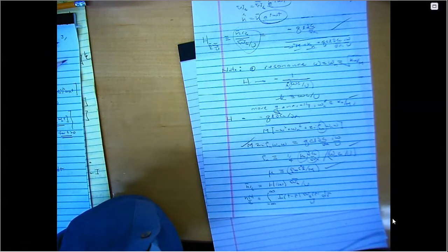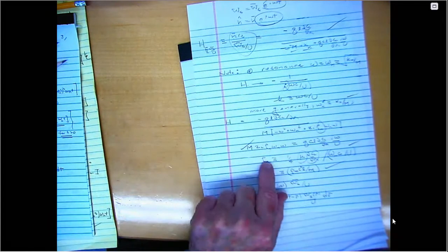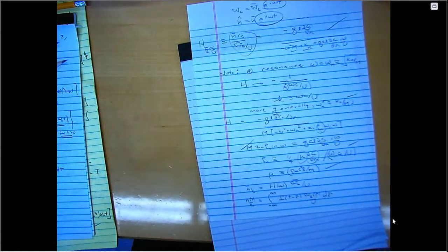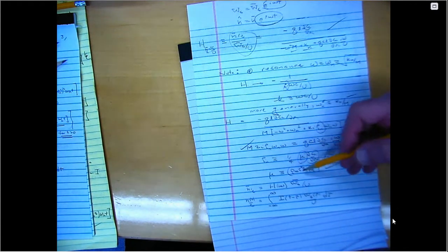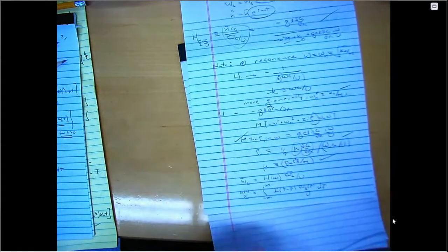In turbine machinery, that number is typically so small that some approximations are made out here. We can't say, if we set mu to 0, we're going to throw away all the damping, right? We don't want to do that. It changes if you're doing this in liquid. Oh, yeah, that's right. In water, this would be a much bigger number because rho would be a much bigger number. So hydrofoils have one kind of mass ratio, and turbine machinery blades have another one.